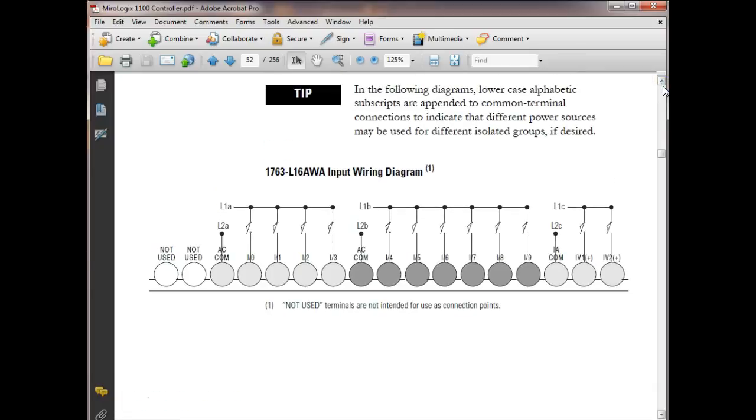So this version right here, if you get this guy, it's what? AC. So that depends. Like we said, when you're dealing with AC, syncing and sources don't come into play. But shouldn't the AC be on the line one part, on the L1? It is L1. Yeah. This is L2. Usually in motor controls, we call L2 our common, and we call L1 what, in house wiring, we call hot. Hot, right.